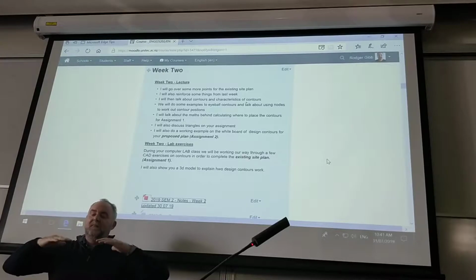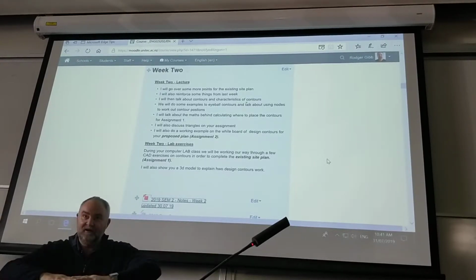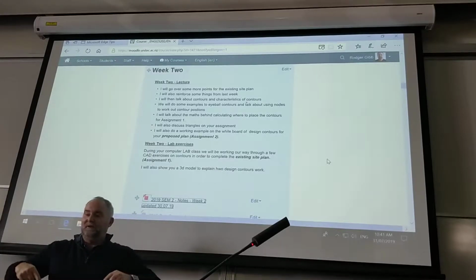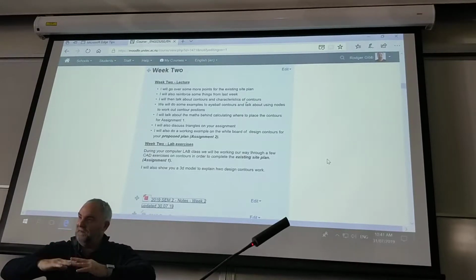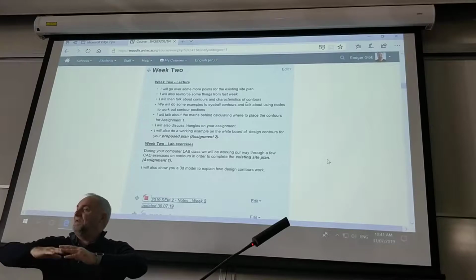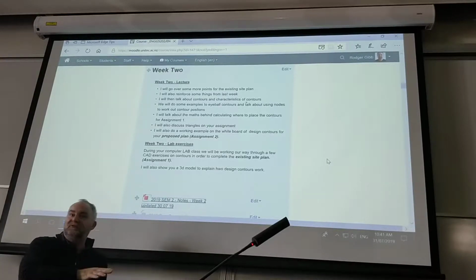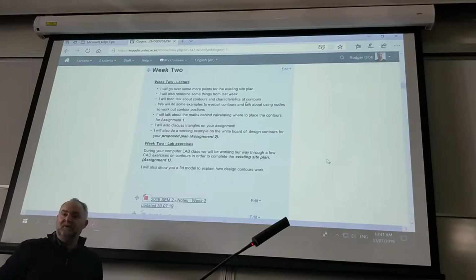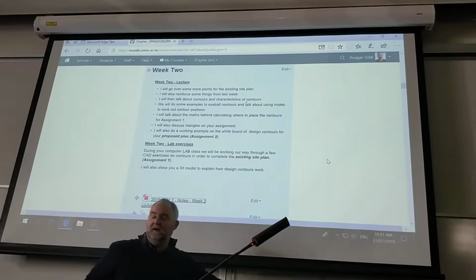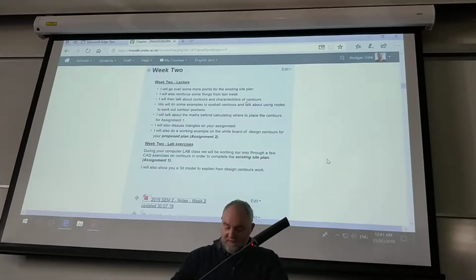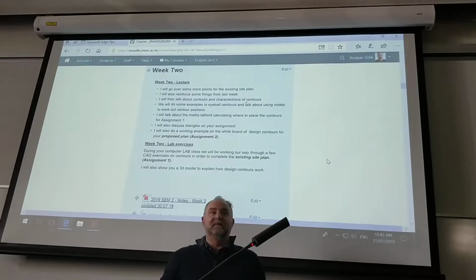Imagine if I was to put a tennis court there and just rested a platform of, say, 10 metres by 10 metres into the ground at a certain level. Some of it will be dug into the bank, and some of it will need to be supported by some fill. Okay, so that's the calculations we'll be doing on the board here graphically, and we'll show what that would look like in plan view.